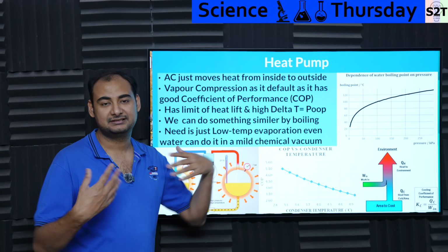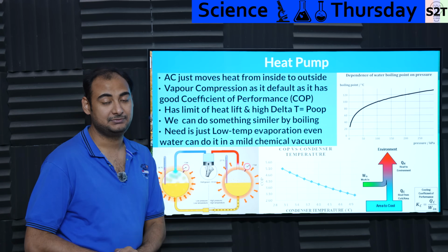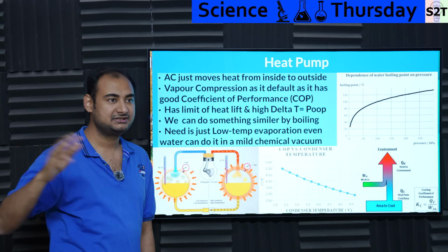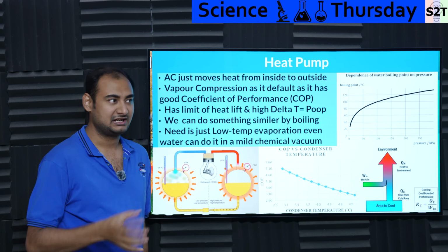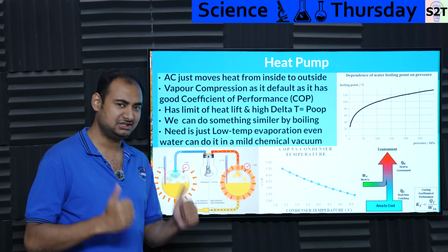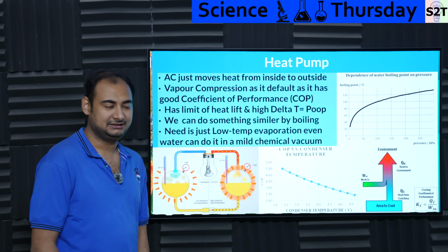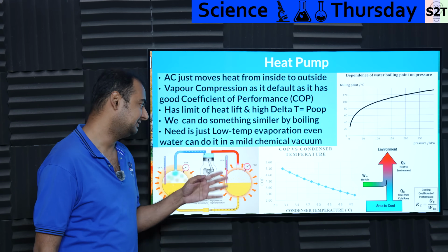So condensers reach a point where it's like, bro, I can't dump heat, and the delta becomes a very problematic thing. Meaning in India, the same AC, like I had this AC, it's the same AC if the outdoor was not hot enough. Basically, let's say it was only 35 degrees Celsius and I wanted 25 degrees Celsius indoors. It will be fine. It will be dandy. Enjoy, have fun. But the moment you change it, it's like, woof, the AC has to keep running for longer. So there is a fundamental limit.